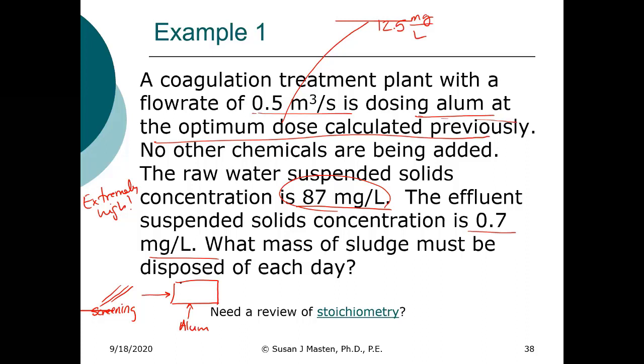It's a process where we want to ensure that our coagulant is evenly dispersed in the water. Exactly. So we have rapid mix, also called flash mixing. And from there, we go into what unit process? Okay, so in the next unit process, we want to slowly mix to allow these particles to come together and to aggregate. So we want to produce bigger particles.